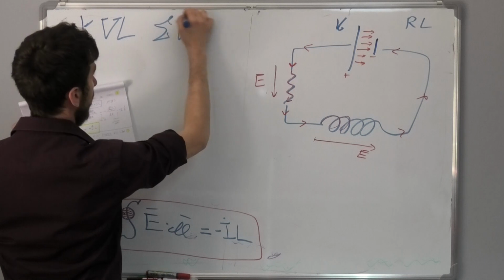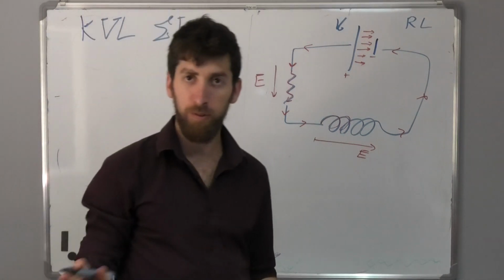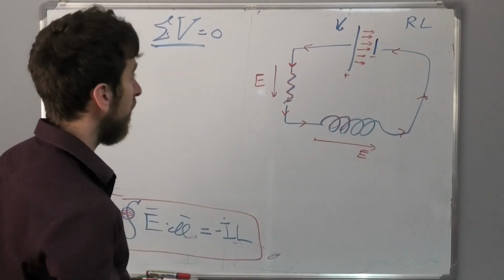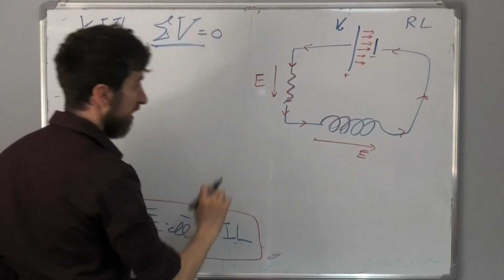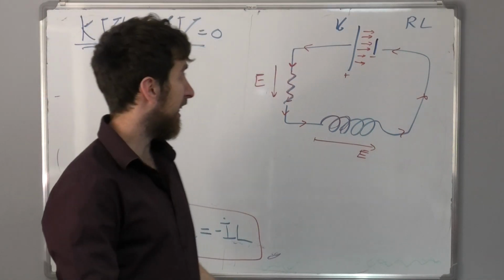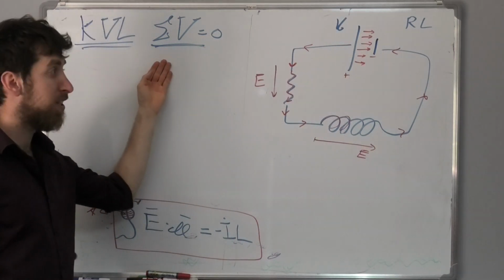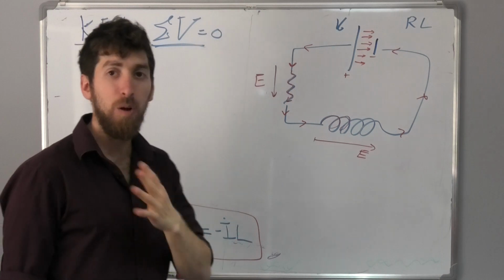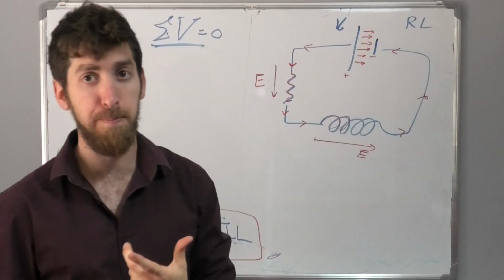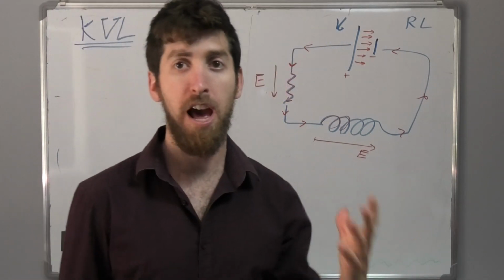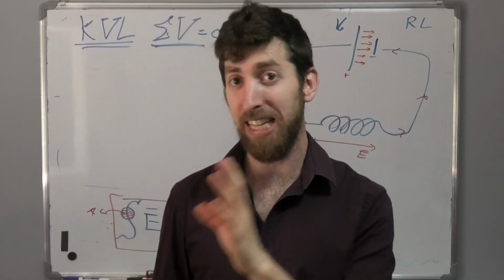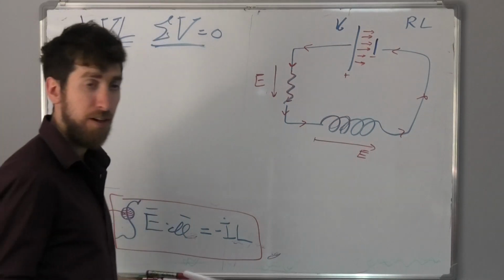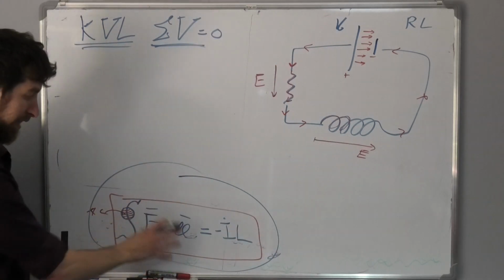which states that the sum of voltages equals 0, and I don't like this rule at all, okay? I'm going to say why. First of all, this idea is not true. It doesn't hold when you have an inductor. This law is incorrect when you have an inductor, so this is one reason. The second reason is that it's really complex to understand what the signs are. I put plus this voltage, minus this voltage, it's not that clear. And the third thing is, this law is not basic. I always love to work with basic ideas, for example Maxwell's equations, Faraday's law, Gauss's law, and from that understand what the limitations are, what idea I can take and what idea I cannot take. This law is not that obvious to me, so I recommend you use Faraday's law in this configuration for every cycle.